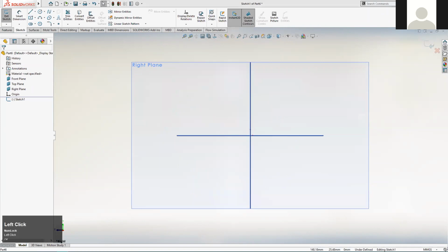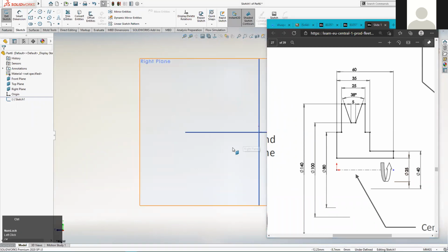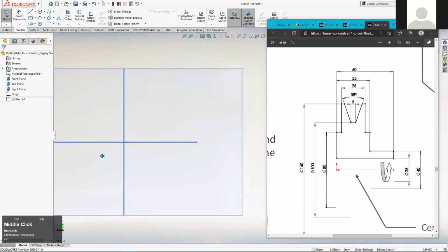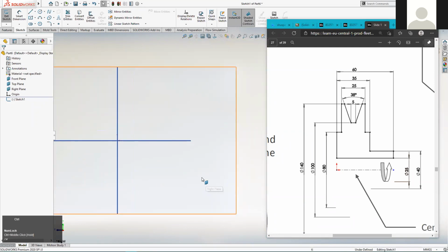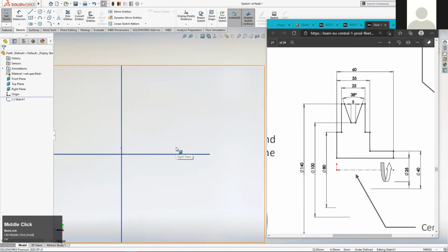I'm now going to bring this back onto the screen and just attempt to pin it there so it doesn't disappear. Has that worked? Yes, it has. So I'm going to try and sketch over on the left here, have my reference pinned over on the right. And then what am I going to do first? Well, first thing, every time you create a new revolve, put the center line in. Get into the habit maybe of putting it in as the first feature. And you can see the center line on our reference is locked to the origin at its left-hand extent. So that's what I'm going to do.